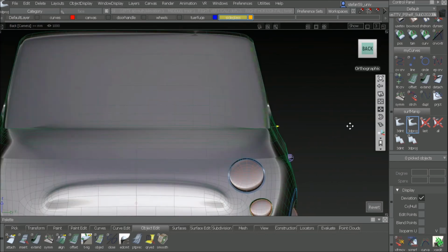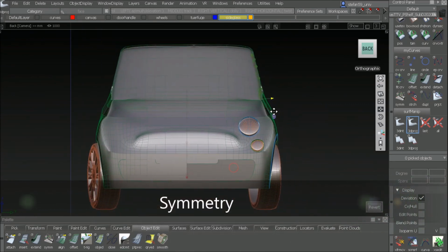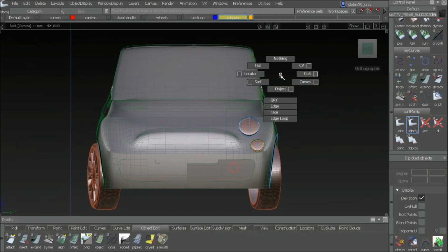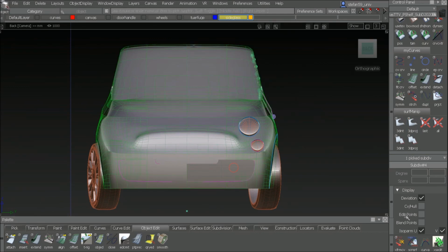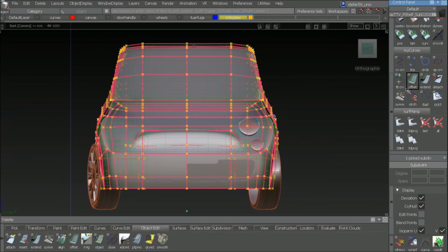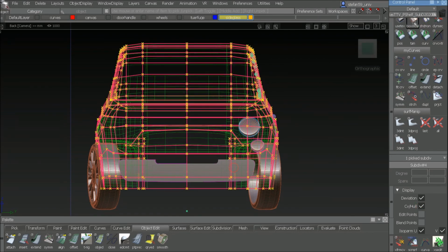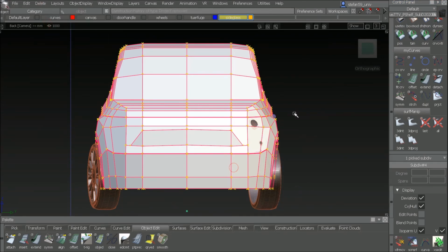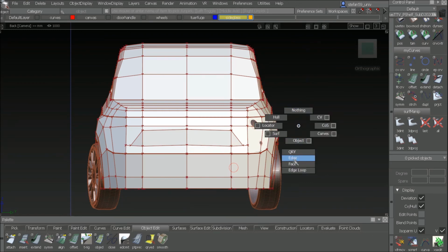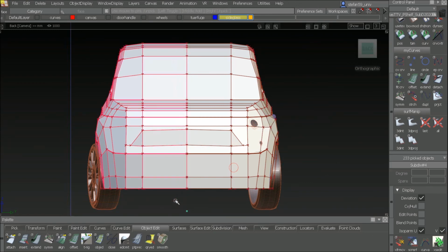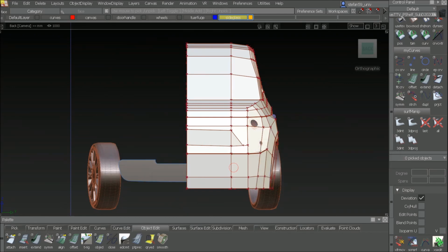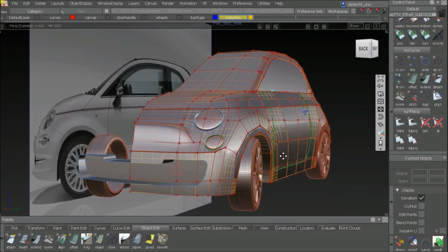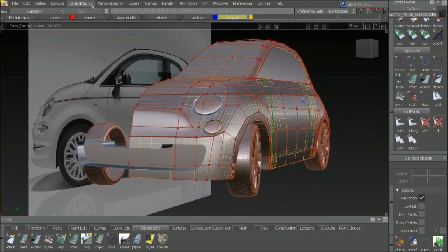We only have half of the car, of course. So we need the second half too. So switching off all the controls of everything, then picking the object, which is the SubD, with the CVs on, and switching to box mode. Delete the history in this case, and then delete half of it. All right, back to smooth mode, and putting everything on this side on a symmetry layer.